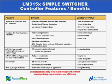The fixed versions, however, make smaller size solutions because they don't need external components like the resistor divider and an additional capacitor. This reduces the size by 4 components. Power-wise, an efficiency of 93%, 95% is easily reachable. And they all have the same input voltage range from 6 volts in to 42 volts in.